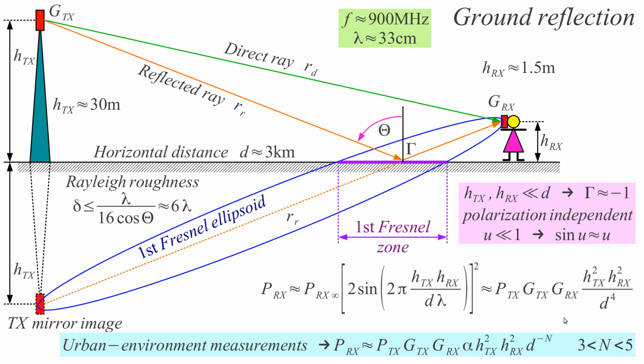So these measurements actually fit this formula very well, with some corrections for the particular town, particular kind of buildings, because it's not the same if your building is made of cardboard or if your building is made of steel reinforced concrete. So that's quite a difference here. So this is a significant amount of loss here, d to the fourth power, but it's actually useful for the phone companies to make more money from the same frequency spectrum they have allocated.